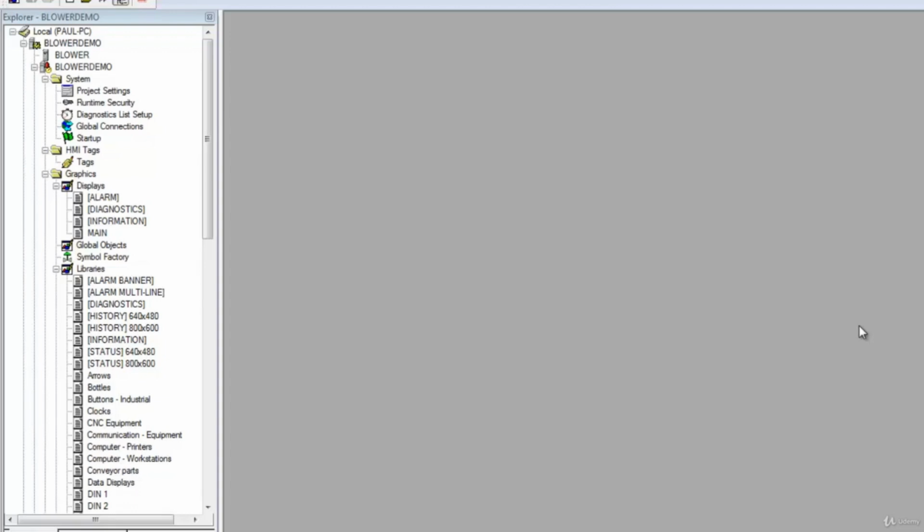The last thing that we want to look at within this HMI project is alarms and notifications. And I'm going to make a very short lecture of this just to show the basics of setting up an alarm inside of an HMI. Depending on the HMI you're using, of course, the alarm setup procedure is a little different, but it all comes down to a tag and some type of notification, and then the options to either silence the alarm or reset the alarm.